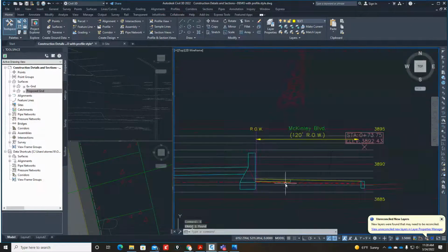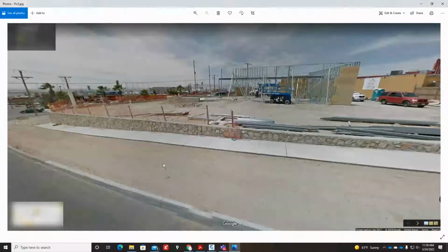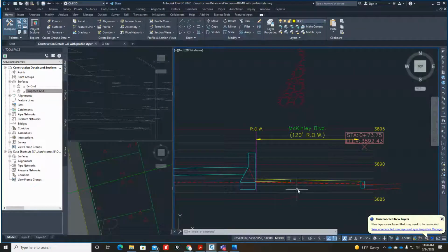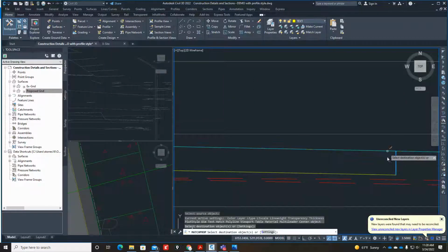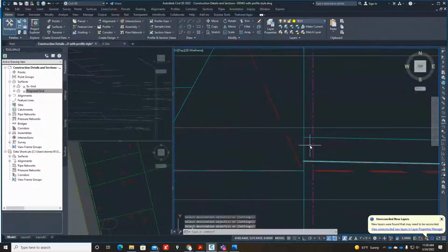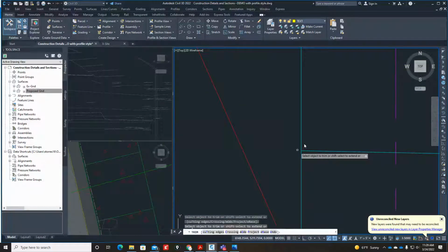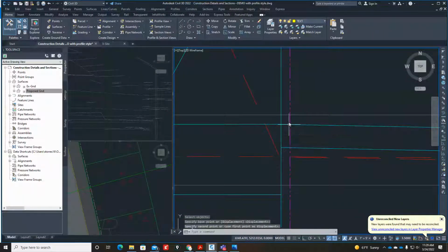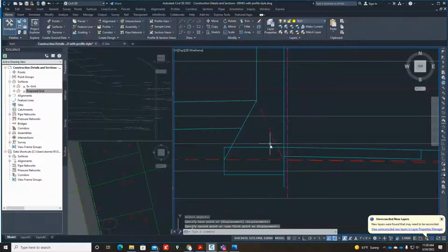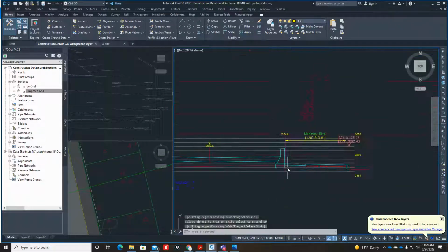You don't need this little section view. So there's actually a little bit of fill right in here, and it kind of looks like it. You can see how they filled in this little area with dirt. So that makes sense. So we're going to have to adjust our section view a little bit. Our retaining rock wall won't be down to here, but I don't know how to tell you this: you try to be as exact as possible, but sometimes you're going to be building it a little bit differently. But nonetheless, let me go ahead and just move this guy up here, right in there, because that's usually what gets retained, from this level down to this level. Okay. And there we go.